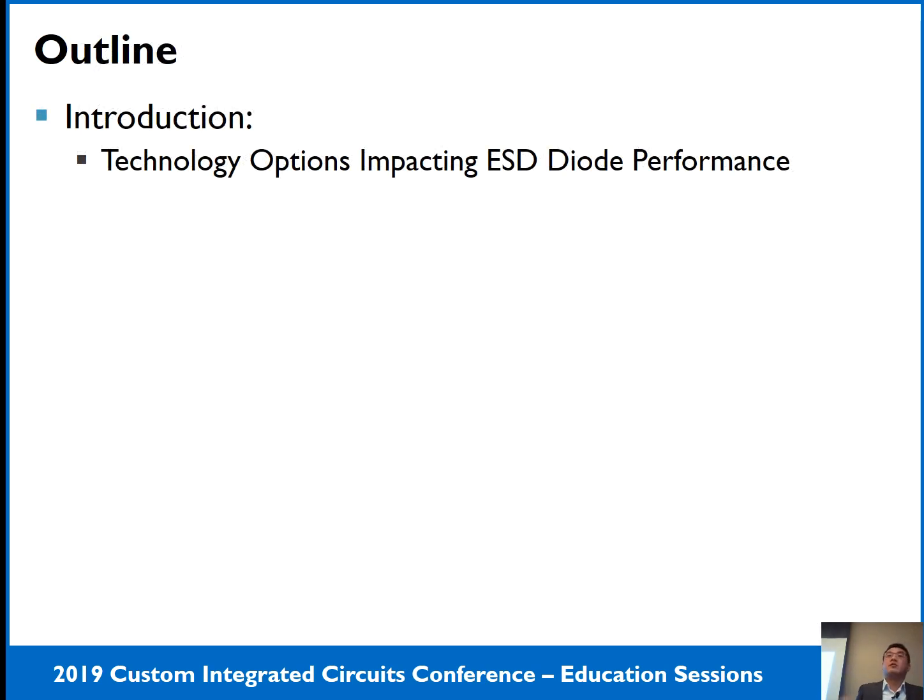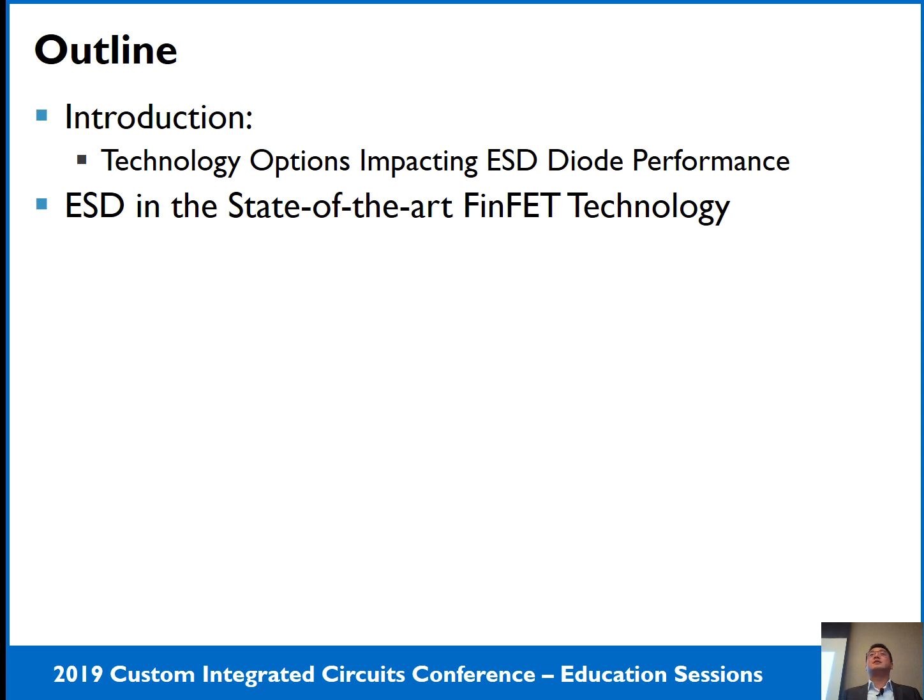So it's the outline of my tutorial. First part is introduction. I will introduce how technology option impacts ESD diode performance, mainly based on our past learning. Then we will look at the ESD diode performance in state-of-the-art FinFET technology. First, we need to know what are the new process options in the state-of-the-art bulk FinFET technology.